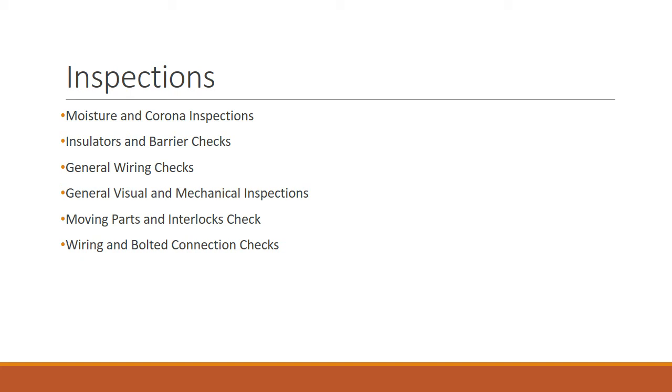Now, the fourth type is just your general visual and mechanical inspections. For this, one should examine the switchgear or switchboard's physical, electrical, and mechanical condition, as well as its anchoring, alignment, grounding, and needed clearances. Verify that the equipment nameplate data fits the project designs and requirements while performing acceptance testing if you are deploying or commissioning new switchgear. This is significant since switchgears are designed and rated for certain uses and should not be used for anything else unless the manufacturer has specifically approved of it.